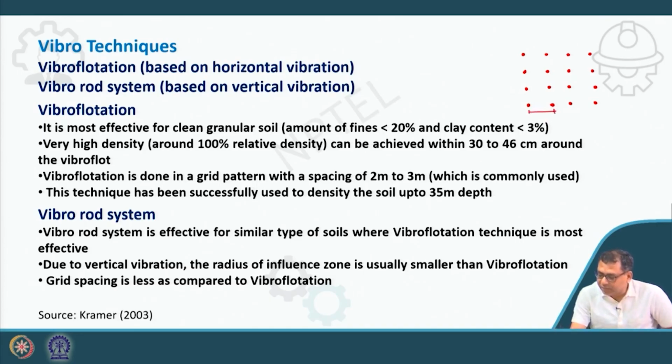At every grid point we insert the vibro float and provide the vibration. Then again we go 2 to 3 meter apart and do the same. This technique has been successfully used to densify soil up to 35 meter.